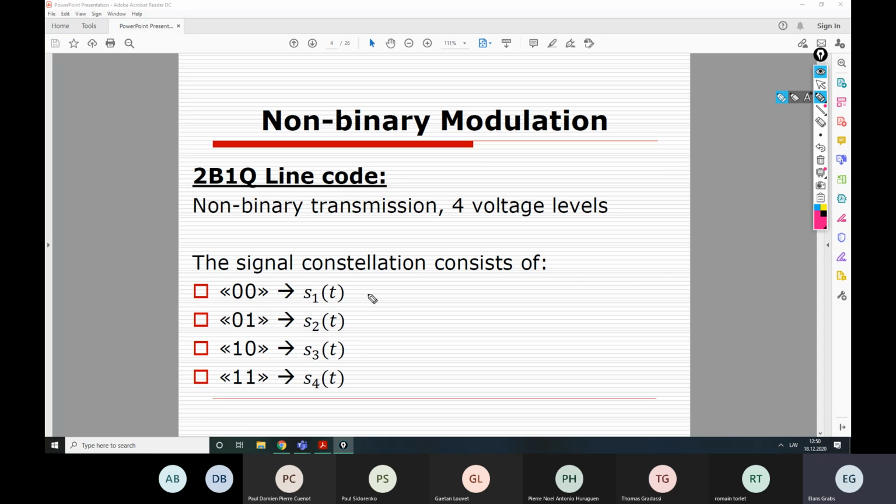For example, they can have different amplitude. So basically here we, for example, would have 5 volts. Here we would have, let's just say, 2.5. Well, actually, let us make it uniformly distributed. So here we will put 6 volts. That would be 4 volts, 2 volts, and 0 volts for amplitude of the carrier signal. And that voltage is then multiplied by the carrier signal with some carrier frequency, F0. Right? And this is basically amplitude shift keying with 4 different amplitude levels from 0 to 6, right?